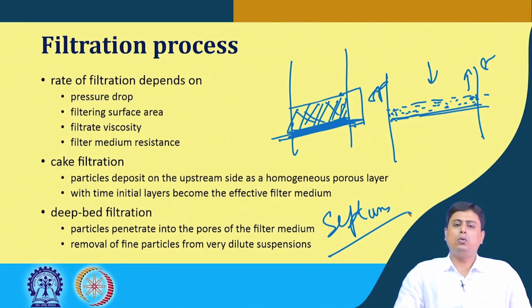So, if you want a reusable filter media, the particles or pores have to be cleaned in deep bed filtration, and in cake filtration, the cakes have to be removed from the top surface of the filter media, and it has to be reutilized after a certain period of time.